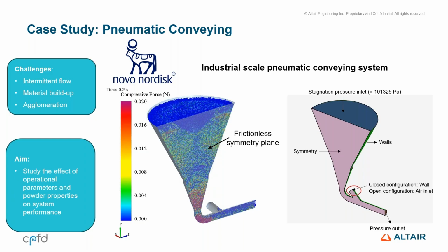These problems can sometimes be traced to this feed hopper that we're looking at here, where processes like arching and rat holing result in intermittent discharge and pressure surges. Developing an understanding of the complex interaction between the operating conditions that are applied and the bulk solid properties that give rise to these phenomena can lead to an improvement in process operation. However, relying only on physical experiments can be expensive and time consuming. Therefore, our customer looked for a numerical model, which we see here.